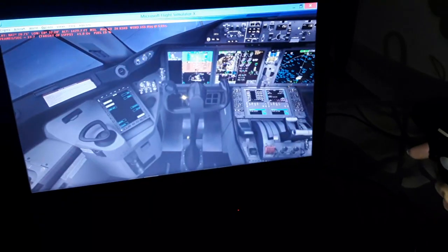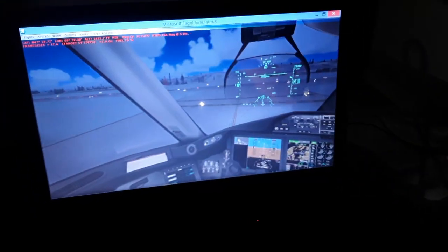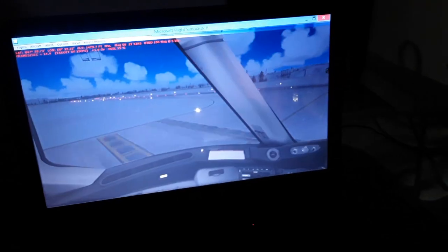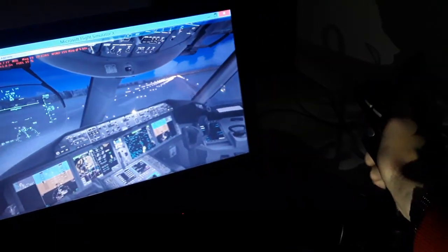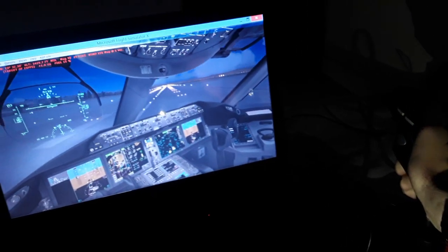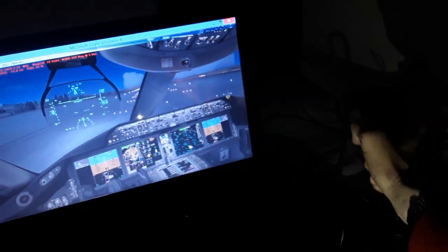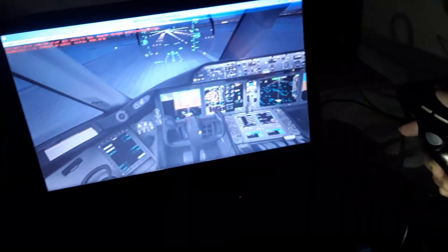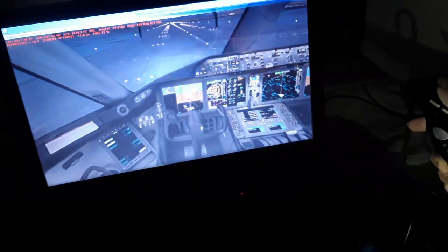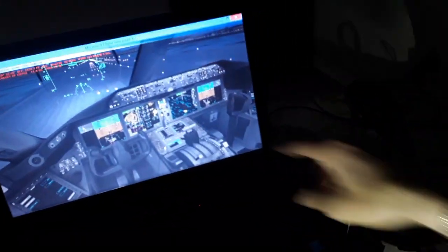We use the tiller for steering again. So it tucks into the runway like this. So align with the tiller again, like this. Advance the thrust levers, take off, go around over here.